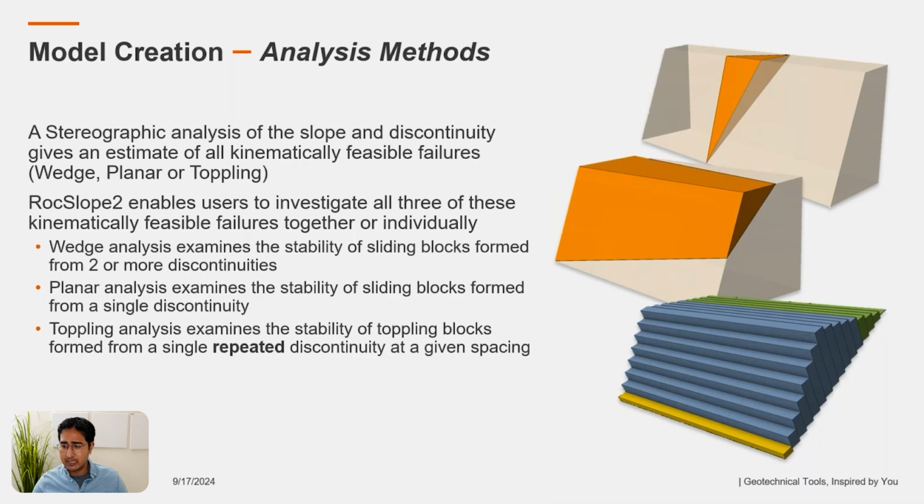Planar analysis examines the stability of sliding blocks formed from a single discontinuity. And then you have your toppling analysis, which examines the stability of toppling blocks formed from a single repeated discontinuity at a given spacing. Any one of these analyses can be performed independently from one another or jointly by using the same set of model inputs.